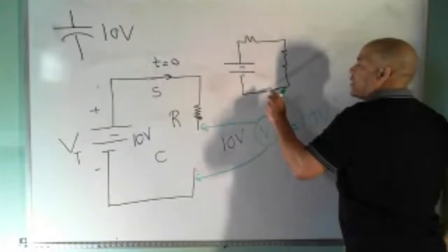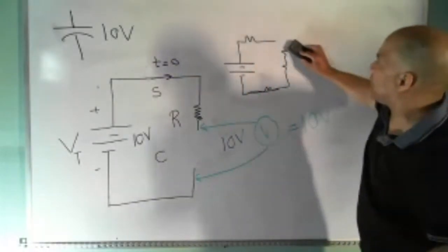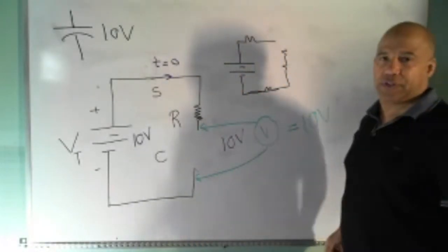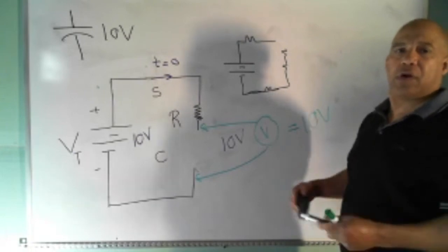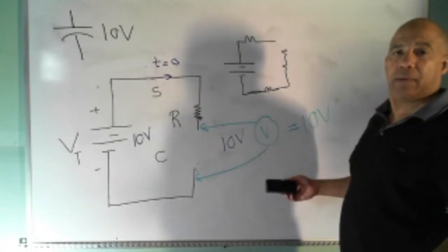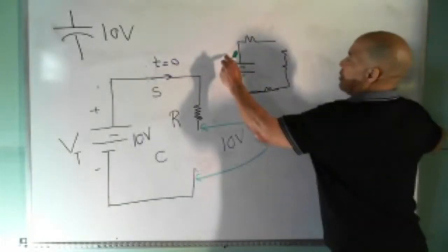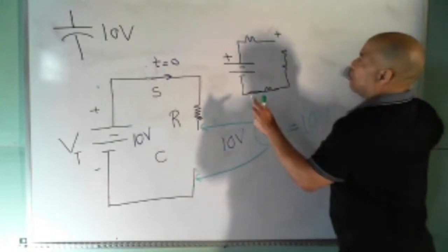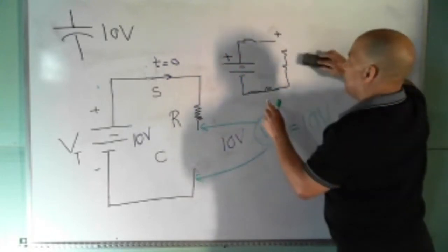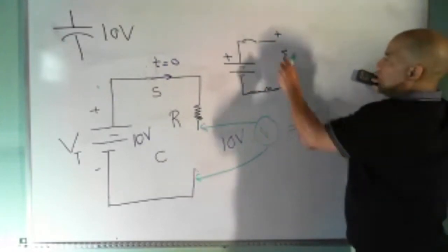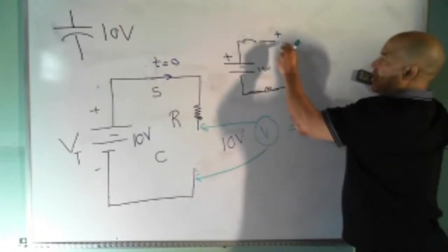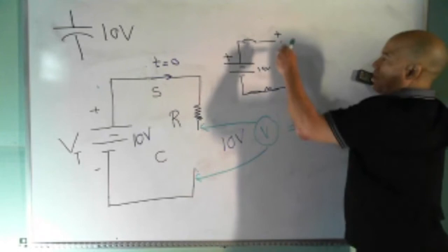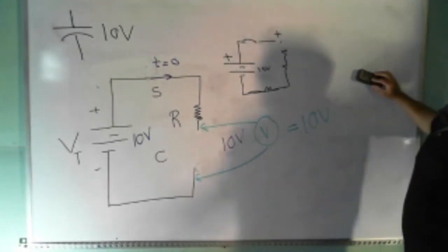that when you have a resistor with no current, if I open this up, no current can flow in the circuit. A resistor with no current going through it is equal to what? A wire. A piece of wire. So basically, this wire now is an extension of the positive terminal. You can replace that with wire. And all of these are just wire. So if this is 15, this is 15, because the voltage drop across each resistor now is 0, they're equivalent to a wire.